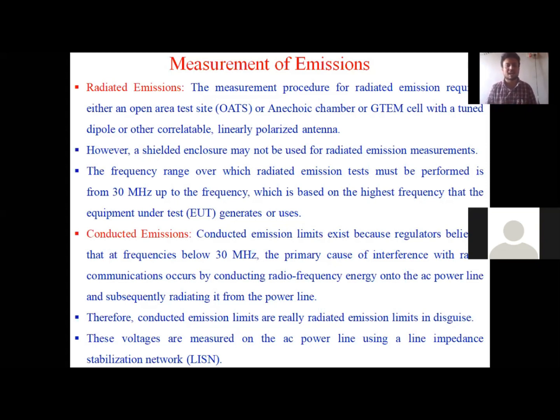While the radiated emission has to be measured in far field. So these are the measuring techniques. Again, this LISN device and a special spectrum analyzer is required for measuring this conducted emission. These devices are really very expensive. That's why in Mumbai, I guess there are only 1 or 2 agencies which are offering these measurements. And whenever you want to launch your product, you have to measure these radiation levels, then only you can launch your product.